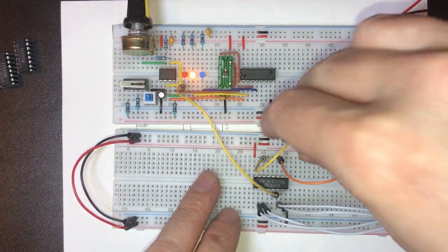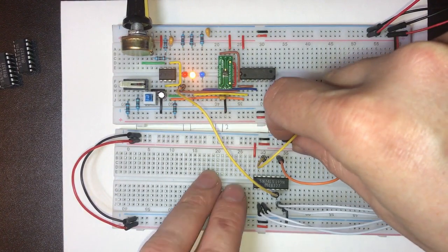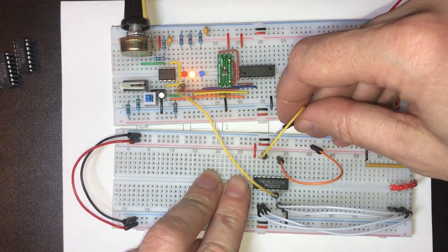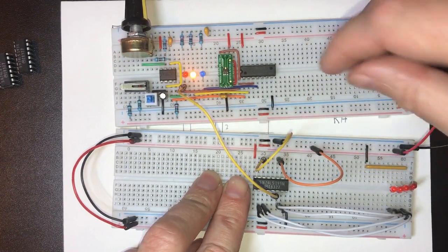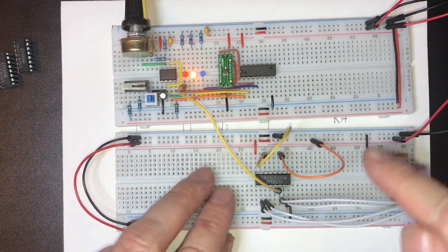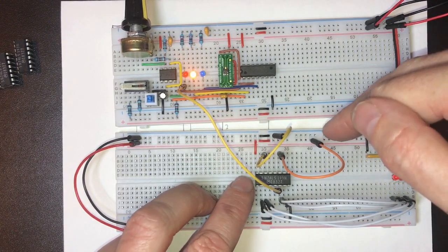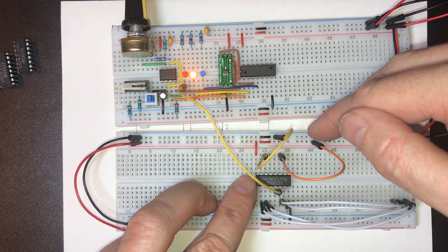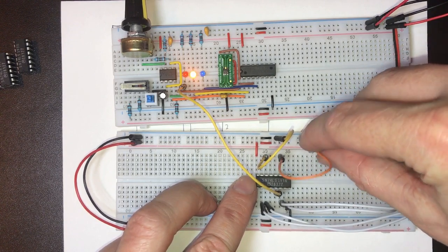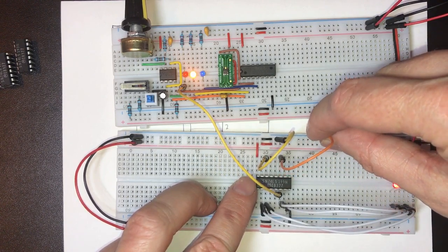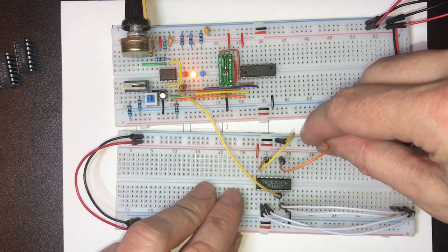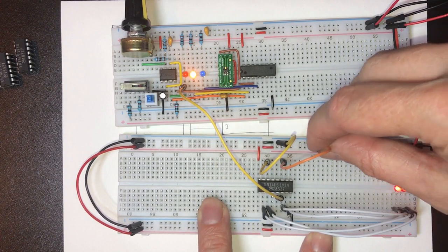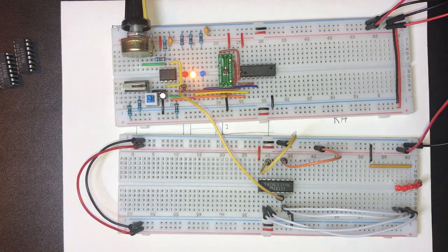Okay, so if I just disconnect this line, the reset should go high on its own, and we go straight back to 0. And for the same reason, if I were to take this parallel load and take it low, all of those inputs are being pulled high, so it will read all ones into it, and then clock it once and it goes back to 0.